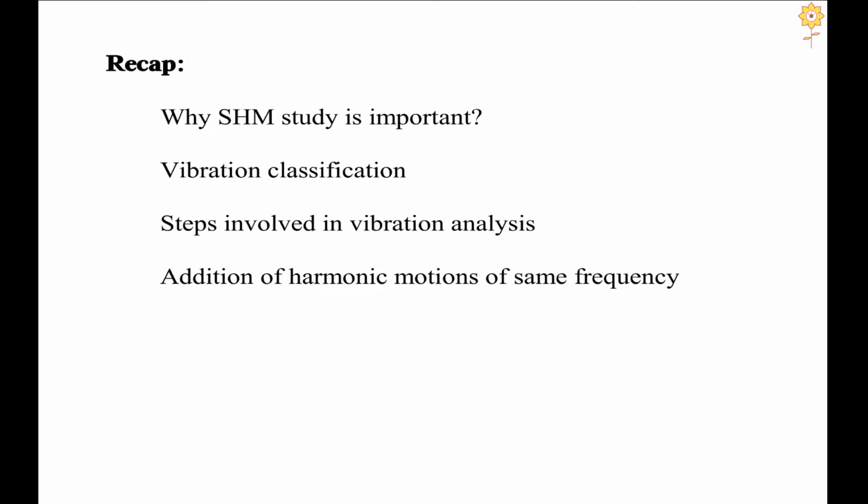The recap. So we saw why the simple harmonic motion study is important, right? One of the reasons was that most of the systems in practical nature closely follow simple harmonic motion if we are assuming that the displacement is very small, right? So we convert a non-linear problem in terms of a linear problem. So we closely approximate the simple harmonic motion. The same we do for mechanical vibrations. And the second reason is that this study of simple harmonic motion enables us to build up various basic shapes of different frequencies into a complex periodic motion by the use of Fourier series.